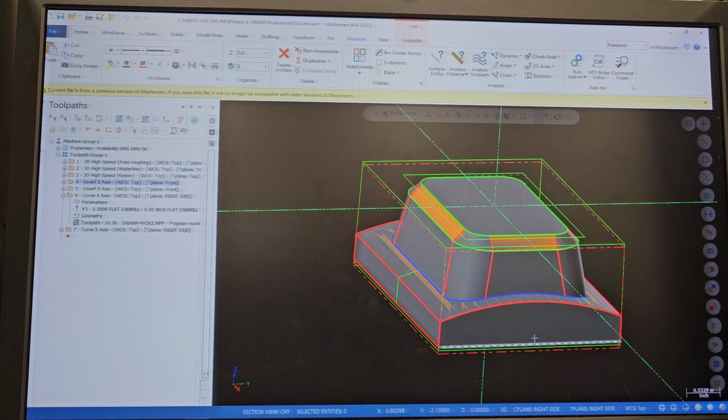We're going to have a SWARF on this one here with the flat end mill, and SWARF on this angle of this wall right here. The rest of everything is 3D toolpath, it's simple, just this SWARF. So that's something new we're going to do on this one.